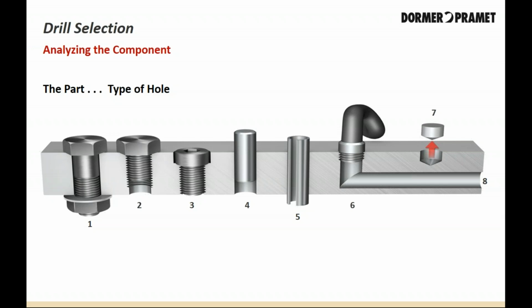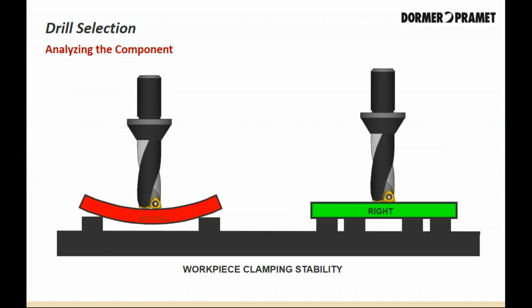The hole type and the required precision affects tool choice. The hole quality can be adversely affected by irregular or angled entry and exit surfaces and by drilling through cross holes, especially when the holes are not centered to each other. Make sure the workpiece doesn't flex or move when the force of the drill is applied. Moving or adding fixture supports closer to where the drilling force is greatest may be required so the part remains stable.